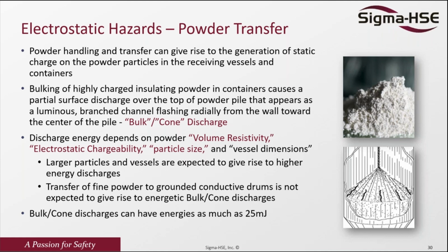And this can generate an energy of up to 25 millijoules, and it can ignite gases, dust, and solvent. So normally we always have an ionizing thread, or something ionizing, which will stay in the middle of the container and will dissipate these charges into the ground. Which is very, very important, and it all depends on the particle size of the material. Higher particle size means higher charge generation. And in case you don't have any flammable atmosphere, maybe dropping it by gravity is not going to create a lot of charges.